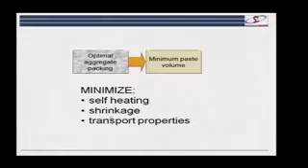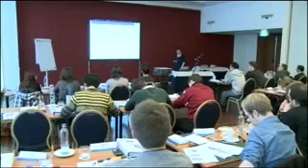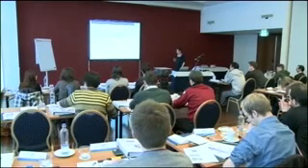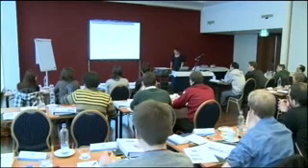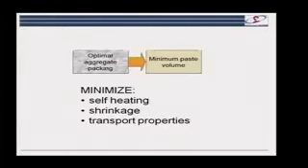That can give you a problem in large masses, so we want to reduce the self-heating. It's the paste phase that shrinks, so again we can reduce the shrinkage, and it's also the paste phase which contains the porosity, which is where the water and other ions come in that can lead to degradation. So for all these reasons, you want to have an optimal aggregate packing to reduce the amount of paste.